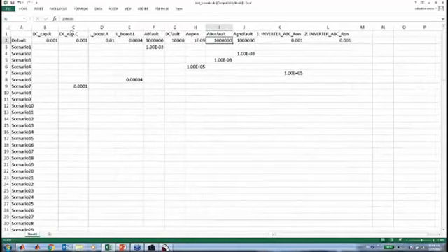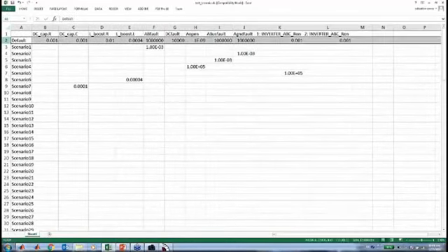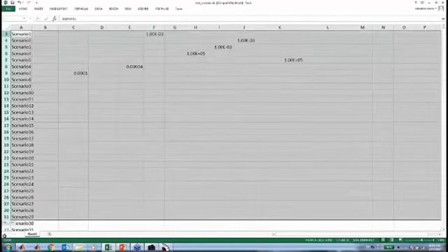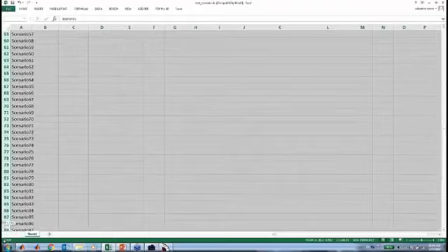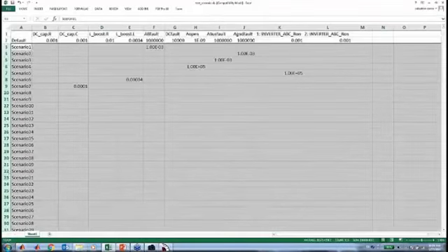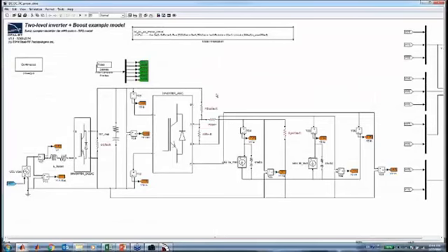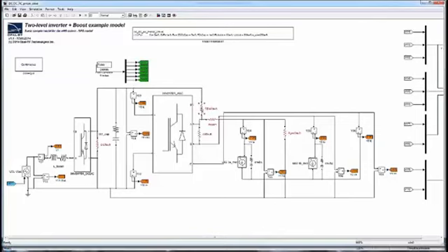Okay, here we go. Now you see this is all my default values for all my elements in the circuit. And if I want to make a modification of my parameters, I have a list of scenarios available here. For this circuit, I can make up to 112 different scenarios. What I've done to my circuit to make a fault is I inserted some resistors here that are not real resistors, but the default value of these resistors is very high if I want to make a short fault. So the base resistor is very, very high, and when I apply a fault, I'm going to put a very small resistor, so you're going to connect the two nets together.